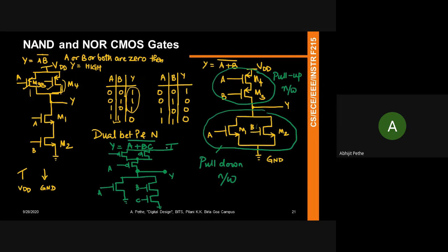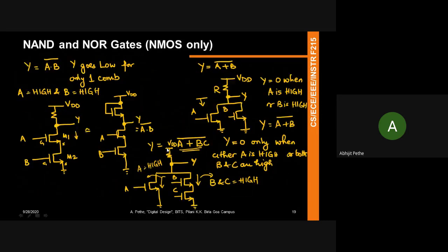So I'm glad Arjun answered the question. So NMOS technology, Shiv, you remember I showed this combination. This is nothing but a way you implement a resistor using MOSFETs. What happens here is this transistor is always going to be on, which means there's always going to be current flowing in the circuit. And so as Arjun pointed out, this is going to always leak current from the supply voltage, so your ICC numbers are going to be very high.